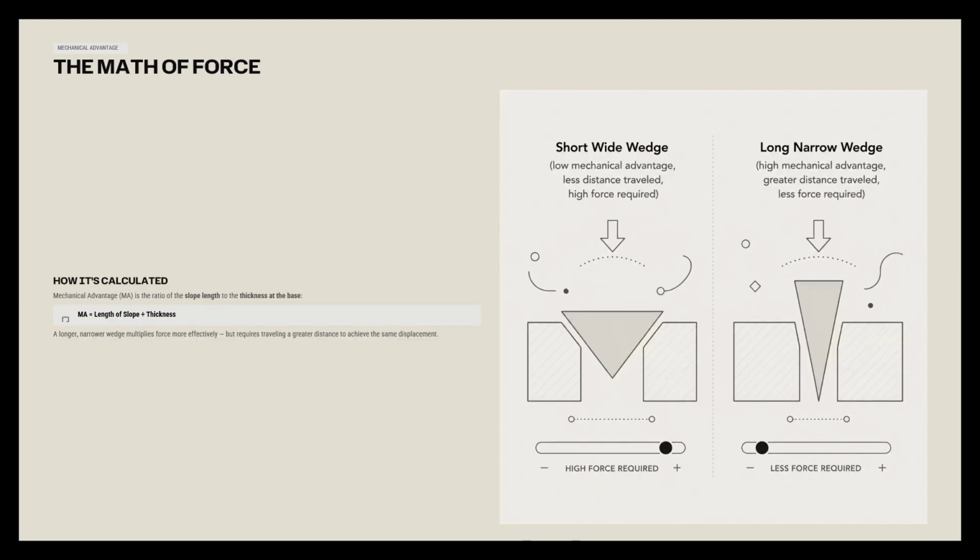In terms of mechanics, static friction and wedge angles play a critical role. A wedge exhibits self-locking behavior when friction alone holds the load without any applied force. Smaller wedge angles increase both mechanical advantage and the tendency to self-lock, while higher friction coefficients improve stability under heavy loads.